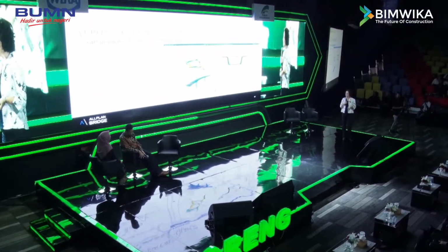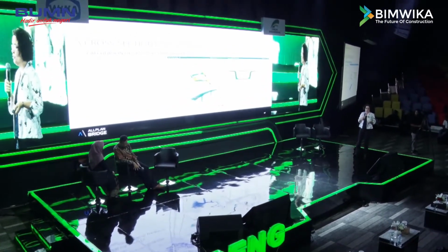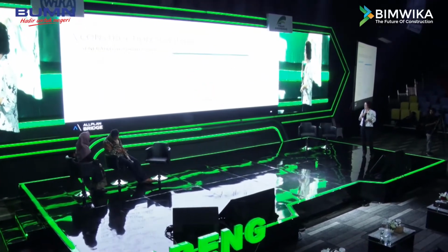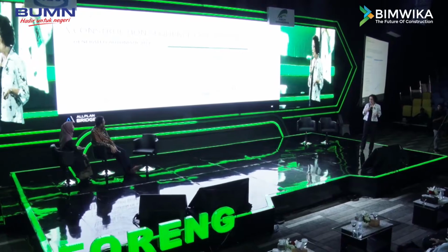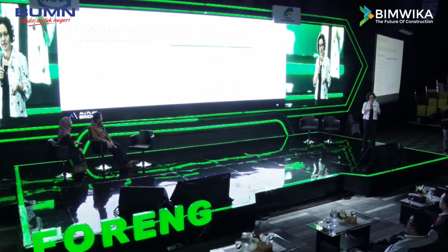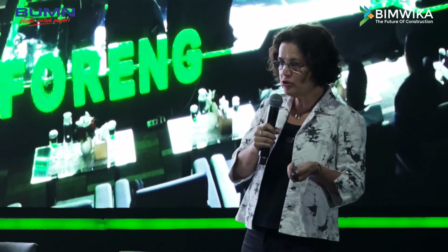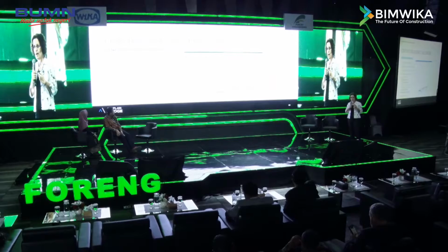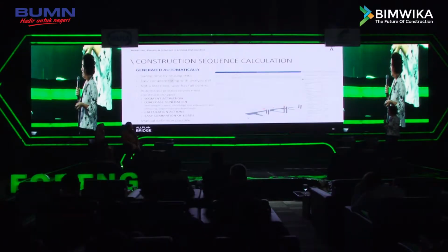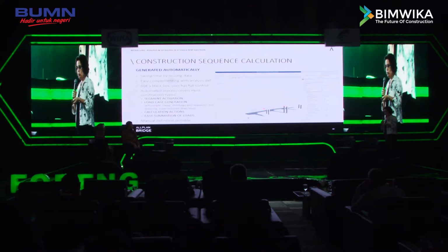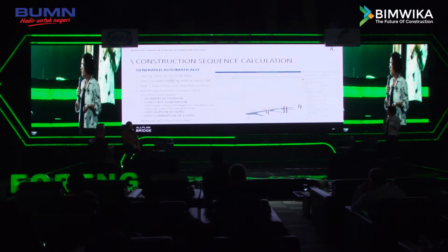First of all, we need to get the cross-section properties detailed, calculated, user-friendly, and also checkable. On another side, we would like to have the calculation of this construction sequence automatically done, but the bridge engineer should not have a black box. He needs to control what is happening with the bridge. It means that we have a kind of load case generation, which was added, which was understood as a load and not a structural element, as a self-weight due to the time schedule, creep, shrinkage, relaxation. Due to the definition of the pre-stressing tendons, it is automatically assigned to the structural members. And in this way, the loads will be automatically prepared.